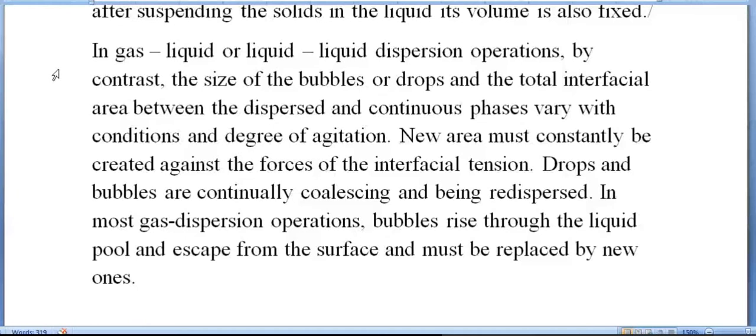The air bubbles go along with the way the flow currents flow. But the majority try to go up because gas is not soluble in water. Gas always moves from bottom to top. So sometimes, if the concentration of air bubbles is more, they may have the strength to change the direction of the flow current also, and dictate it. They say, you also try to come along with us. Then upward currents are formed. That is the dynamism we are looking for for this kind of reactions to take place.